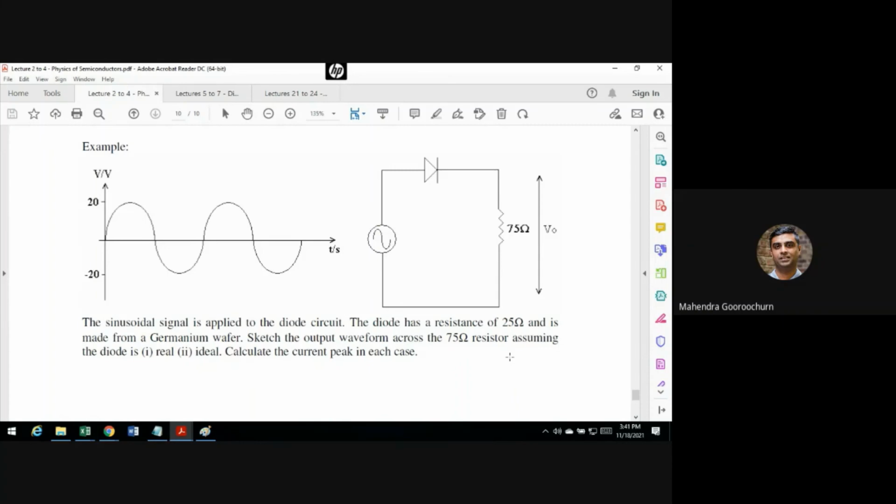So we are left only with the half positive cycles because we know in one half of the waveform the diode is forward biased. This is where it's going to be behaving more or less like a short circuit or as a very low resistance. So current can flow across your 75 ohm resistor, but in reverse mode now, your diode is not allowing any current to flow, or only a very small leakage current. So basically, no current is flowing through the 75 ohm resistor. Using Ohm's law, V is equal to IR. If no current flows, V naught is 0. This is why we've got that.